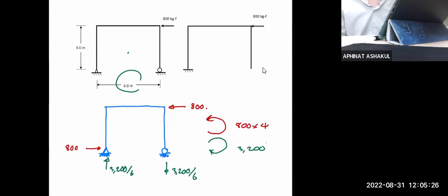Now we have balance with sigma Fx. And we know by balance with sigma Fx that the two forces do not coincide, so it creates moment. So we create moment in another direction to balance the entire system. In doing so, we find out that we also have the vertical reactions. Since we don't have an external vertical load, you know right away that your vertical reactions must be equal and opposite, balancing themselves out. Simple as that.